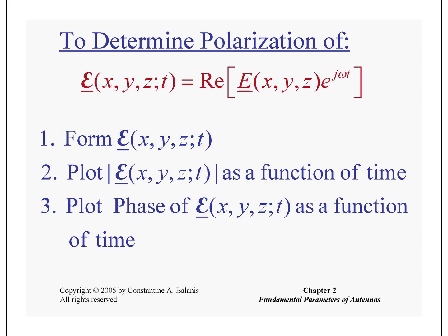Okay, to determine the polarization of the electric field or the wave, first of all, we have to represent the wave in space and time domain format. The equation for the space to time domain conversion is given, that is the red equation. You see that we take the real of E(x,y,z). E(x,y,z) is basically the space domain electric field or phasor electric field.